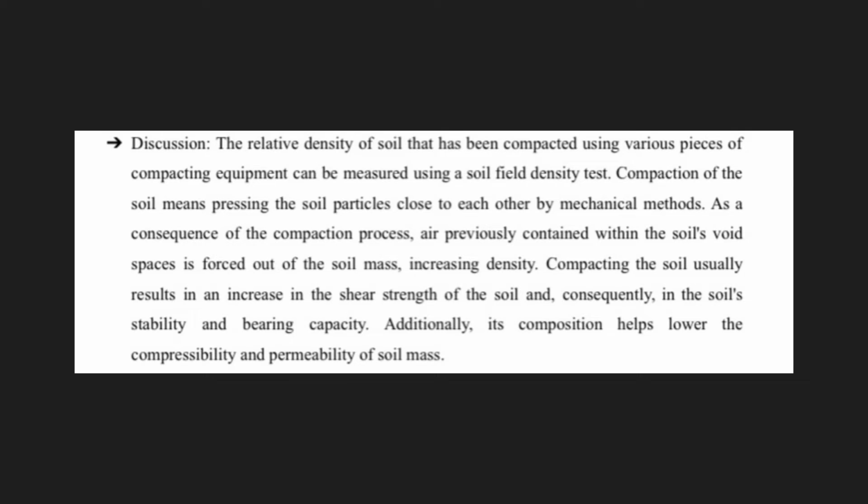The discussion of this experiment is the relative density of soil that has been compacted using various pieces of compacting equipment can be measured using a soil field density test. Compaction of the soil means pressing the soil particles close to each other by mechanical methods. As a consequence of the compaction process, air previously contained within the soil's void spaces is forced out of the soil mass, increasing density.